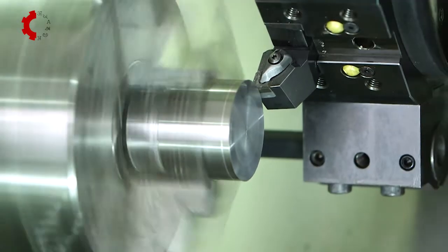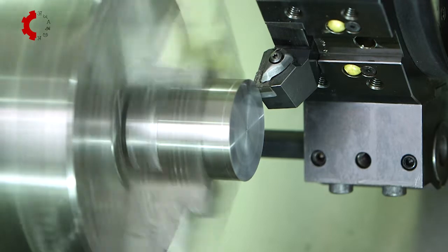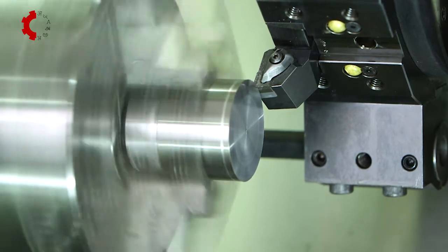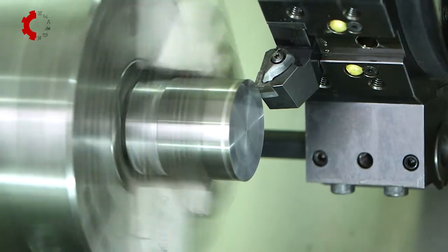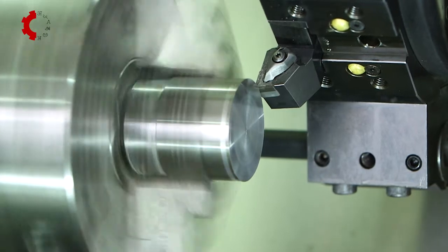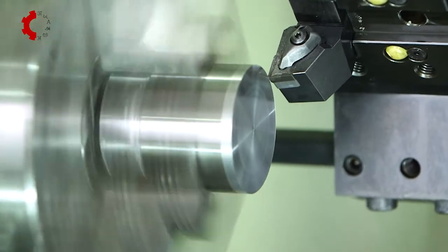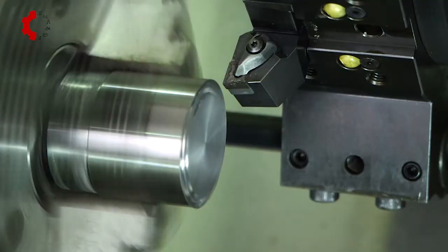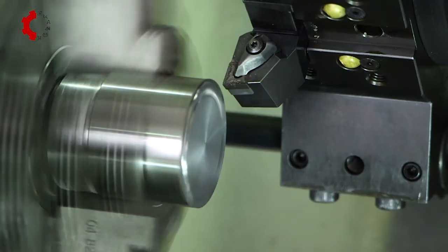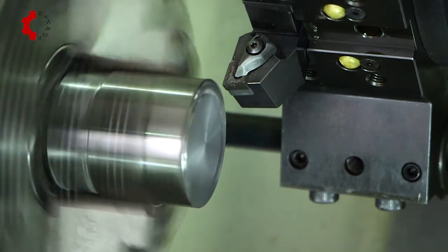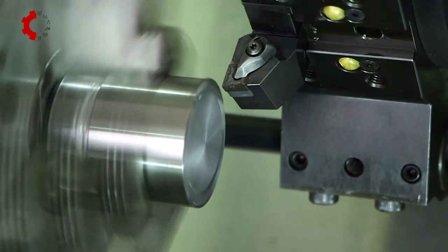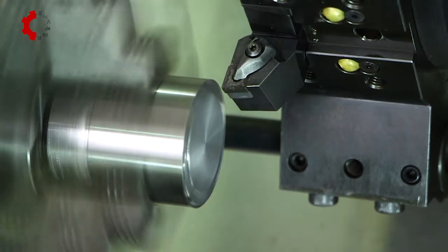the workpiece. Switch MPG to Z axis and move the tool slowly along Z plus direction to clear the front face of the workpiece, taking a small cut along Z plus direction. Switch MPG to X axis and move the tool a little along X minus direction so that it shall take a small cut along the diameter of the workpiece.